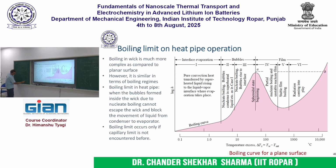What will happen? Some bubbles will start to form. Now, in conventional pool boiling, the bubbles can come out of the liquid, but here the bubbles can get trapped in the wick and those bubbles can then block the flow of the liquid, and that is called the boiling limit. If this happens, then again the wick will dry out, as sufficient liquid will not be able to reach.